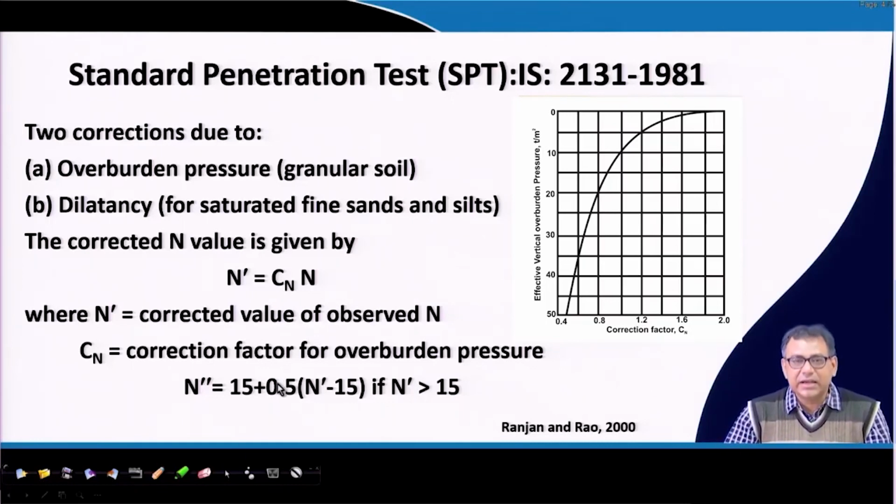In such a case, if we apply any impact on a dense soil, then the soil will dilate. Because of this dilatancy, the soil will expand. Okay? So, that means your volume will not decrease, it will increase, and this will happen for dense sand. It will not happen for the loose sand, it will happen for the dense sand.